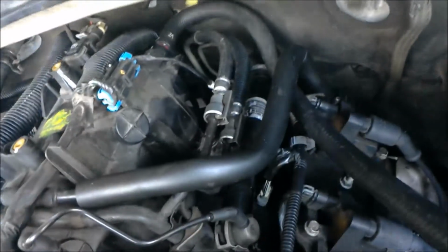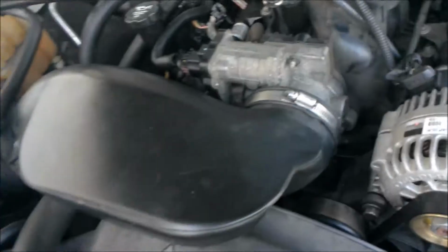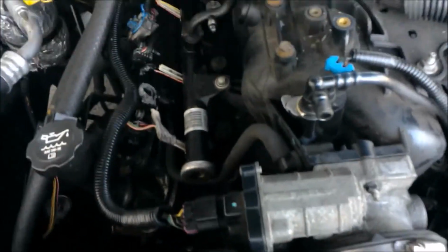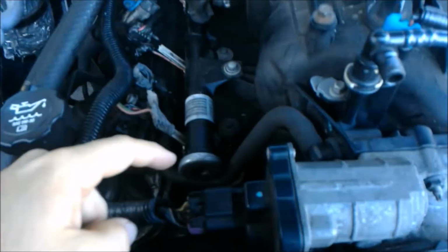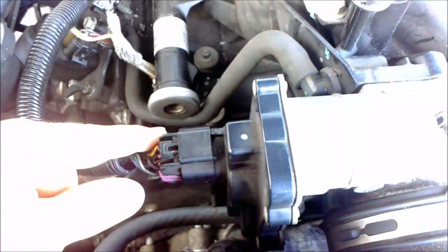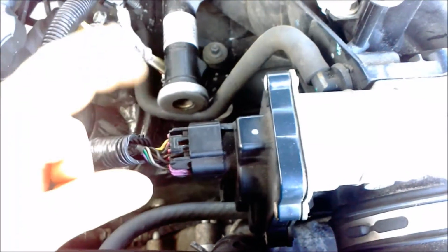So on this Silverado, it's a return fuel system. You can tell by those two fuel lines going right there from the engine to the fuel tank. And then this throttle body right here is going to be drive-by-wire. You can tell that because there are just these wires right here to control it. It's going to be controlled by the computer when you push on the pedal. And the drive-by-cable is going to be controlled directly by the driver from the pedal. And I'll show you that real quick.